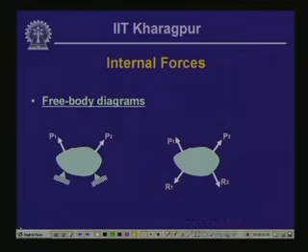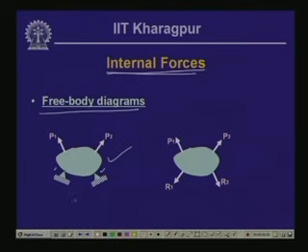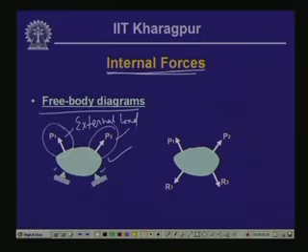Now, having known the body force and the surface force, another aspect with which we will be dealing quite frequently and should be concerned with is the internal force. To know the internal force, we will have to look into one aspect which we call a free body diagram. Let us consider a body which is supported at these 2 points and subjected to these 2 loads P1 and P2, and these we call external loads. So, the external loads are acting on this particular body.